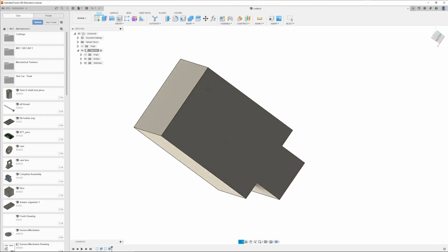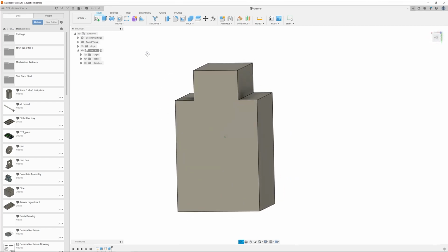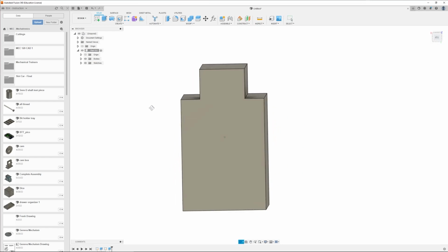And this is one of the basic ways that we can begin to create more complex geometry. And we can do this with basically any enclosed profile of a sketch. Keeping in mind that it is always best practice to fully constrain a sketch, except with a few exceptions that we'll probably get into in about 2 weeks.